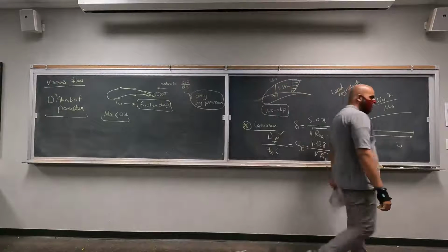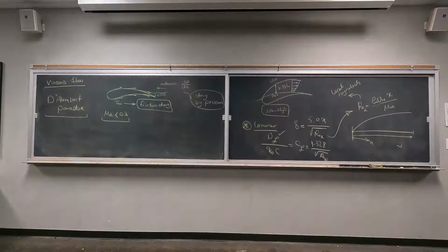It does depend on the surface roughness, right? There is no term here because we are making the simplest calculation you can make, right? But in general, you are moving in the correct direction. To make this equation more inclusive, you have to bring in the surface roughness as well. But we are dealing with a flat plate here, so we are assuming there is no roughness, okay?